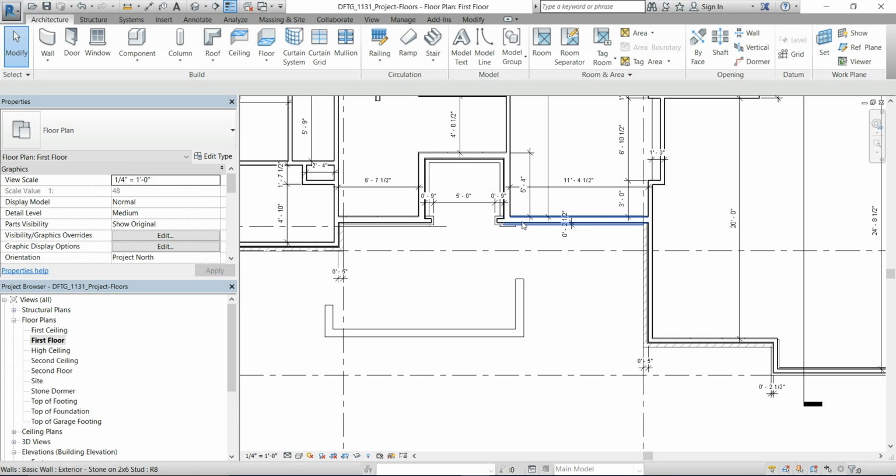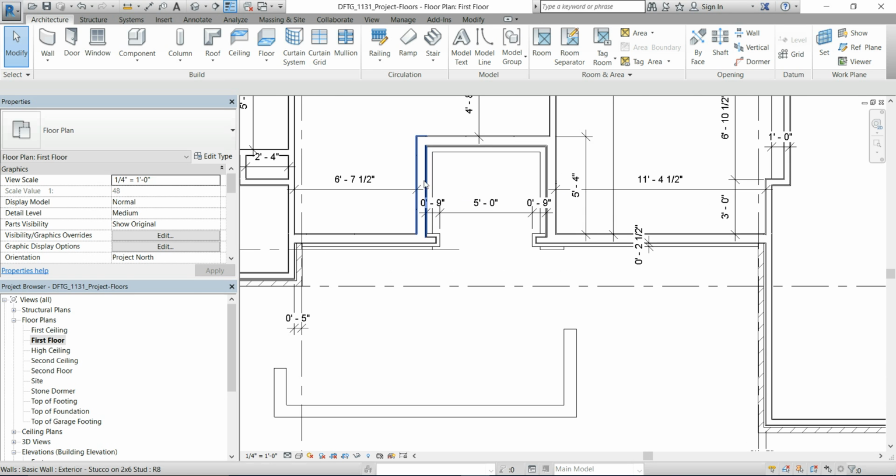And I'm going to assume, looking at it here, it looks like 6 inches on this wall, 6 inches on this wall, maybe 4 inches back on this wall, and then 4 inches coming down this wall and 4 inches coming down this wall. And that's going to rest right on top of, I'm guessing, the foundation wall, because we really don't have a detail that shows us how that works.